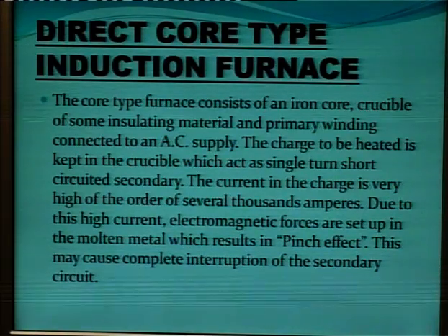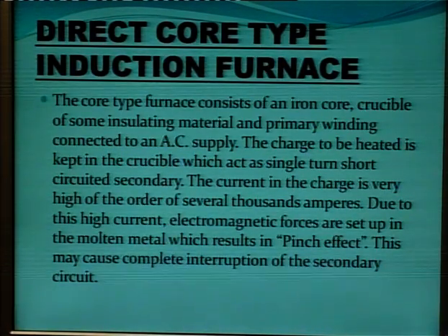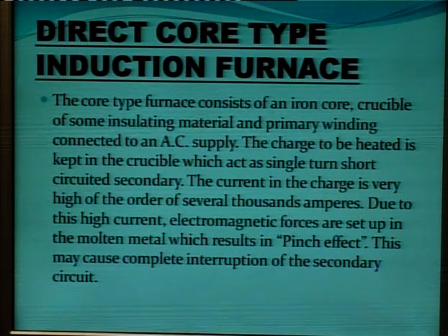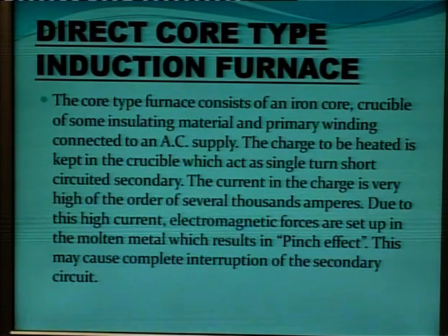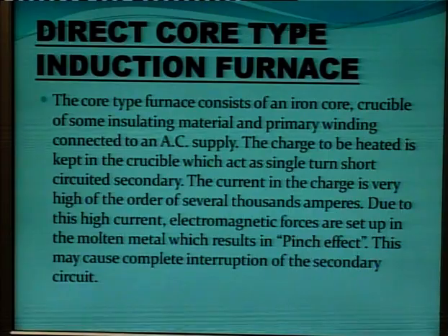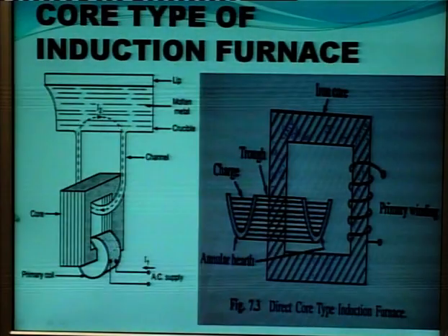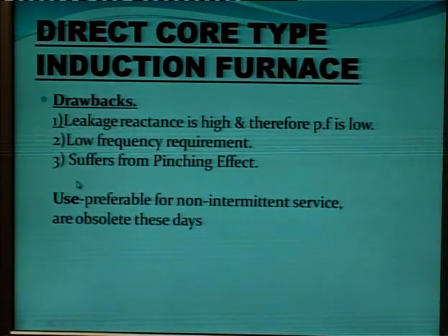Now this pinch effect depends upon the frequency. So as the frequency increases, pinch effect increases. So we must keep the low frequency for the direct core type induction furnace. Now for the low frequency, we must have a separate generator set to obtain the low frequency.